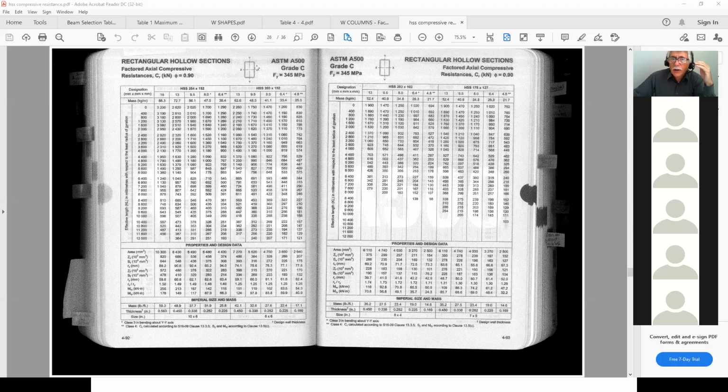That's because, one, it's 450 MPa, so the steel is slightly weaker. And also, the tolerances for when they make these things are a little bit higher than the Canadian ones, and therefore, because of those tolerances, it makes it weaker. So be very careful. I strongly recommend that if ever you're designing a HSS, square, whatever, always choose your size from here, from the American one, A500. That's why if they happen to put some Canadian steel, you'll only be safe.